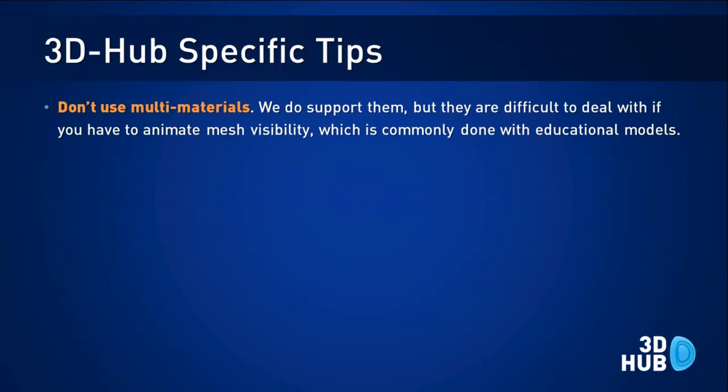Other tips, you can use multi-materials. They do work reasonably well. We don't necessarily condone them as such, because if you want to start to animate the mesh visibility, or you want to actually do unusual things to different parts of the multi-material, that's when problems start occurring. So it's always better to use, we find, separate materials on separate parts of the mesh.